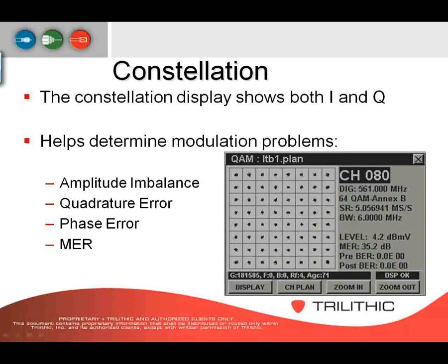Now, reading the constellation diagrams. In a constellation diagram, all of the possible combinations of I and Q form a kind of grid, making it easier to interpret and making different disturbances stand out. The constellation diagram can be thought of as an array of boxes, with each box representing one state of symbols. In perfect data transmission conditions, each received bit would land right in the center of its box, the nominal position for the particular symbol.